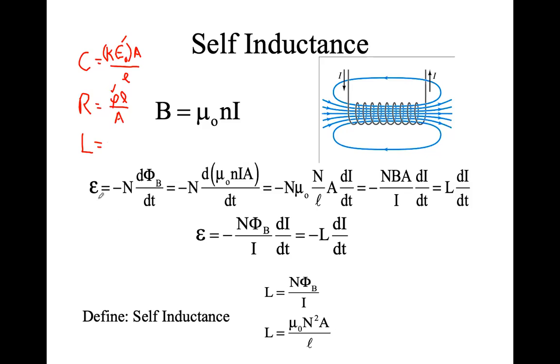All right, so let's kind of go through this. We said that electromotive force is the rate of change of magnetic flux. And remember, this is in a single loop, one turn. In fact, most coils, like the one I showed you 2 weeks ago in the lab, have many thousands of turns on a spool, just like thread. And so the overall electromotive force would be however many turns you have times the rate of change of flux in each of the loops. Well, let's try to get what that flux is. There was an equation when we talked about coils like this, that we used Ampere's law to find what's the magnetic field right in this area right here.